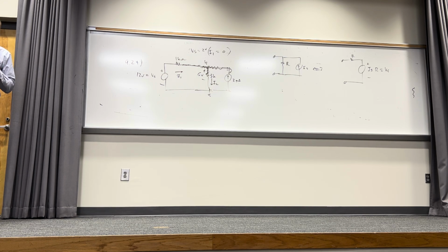And I know some of this stuff can be irritating because it's a little confusing when there are so many possibilities. You get 3 or 4 diodes in a circuit, you start scratching your head. All right? But it's all basically coming down to analyzing a circuit in all possible ways. Like for 2 diodes: both off, both on, one off and one on.